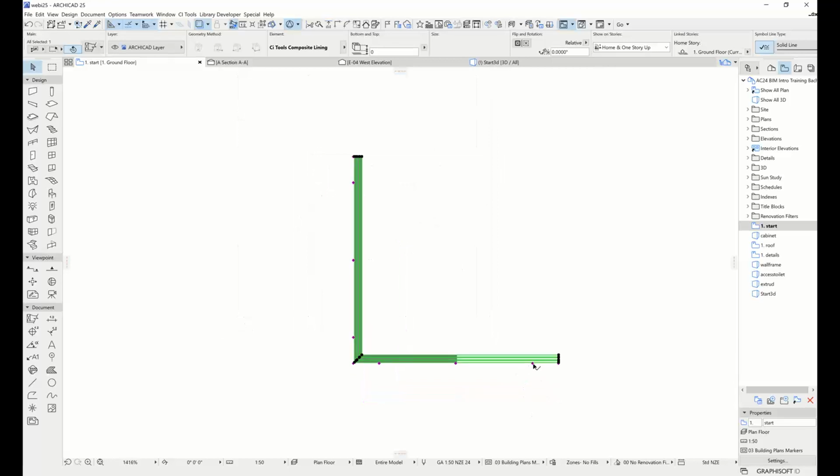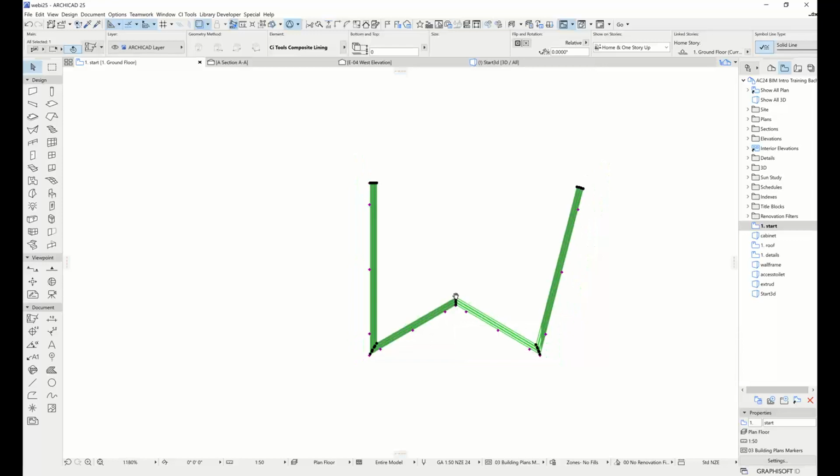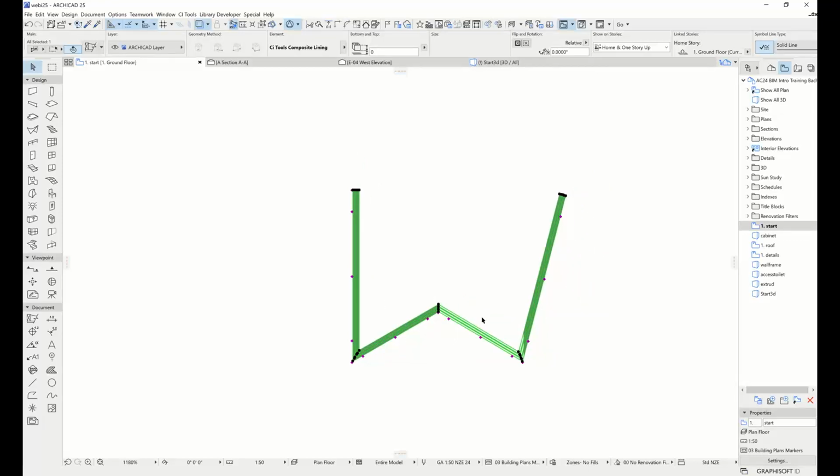And then once you have them placed, you can use the purple hotspots that you see when it's selected to go through and draw that out to whatever shape you might need it to. So they work similar to how the polyline tool does. You can just grab hold of a node in between nodes, and that will add an extra bend to it, or you can move existing nodes to move the ends of them, as you can see there.